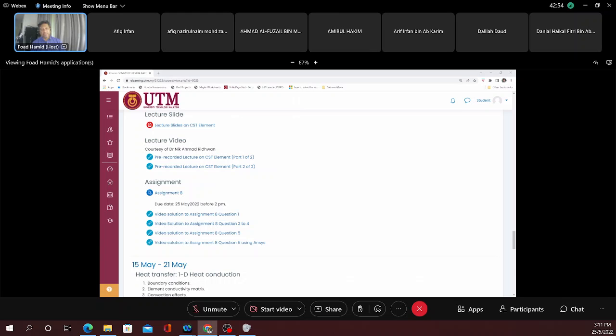Alright, so to verify, to do finite element analysis manually without any finite element method software package. In this case, we are going to use ANSYS, but at the same time, we are going to use a manual approach. It is hoped that students can realize that FEM software package is just an automation tool for the manual analysis. If you look at the manual method, you have to calculate the element stiffness matrix for element number 1, element stiffness matrix for element number 2, and so on, and then assemble. But using software, this is automated. It will be assembled using the software. So this is what I want to show you basically.